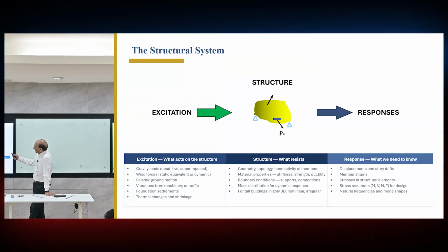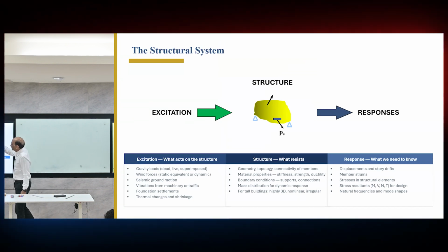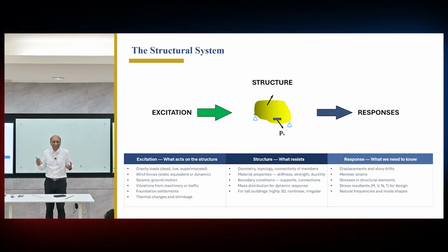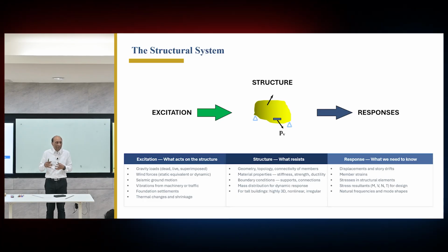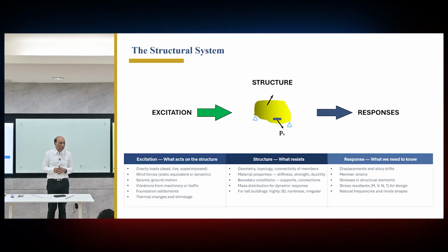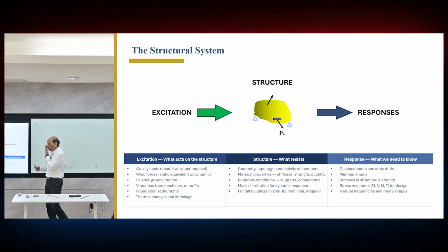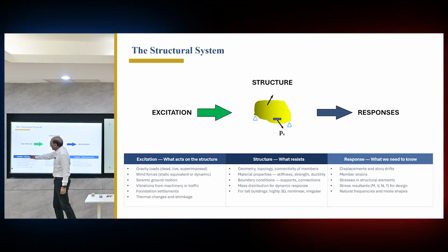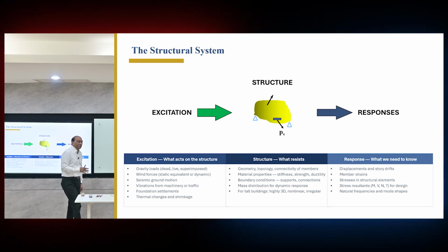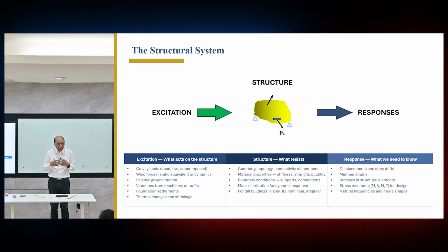So the real structure is subjected to excitation and then creates a response. Excitation is a general term. That means the structure is excited by something outside, sometimes by itself. And that excitation, because we have the action-reaction thing, the structure will respond because of that excitation, and that response is the one that we are interested to fight. So the excitation, whether gravity load, wind load, seismic vibration, ground settlement, thermal changes, anything that you can think of that will change the structure, is called the excitation. So that's why I use the term excitation.